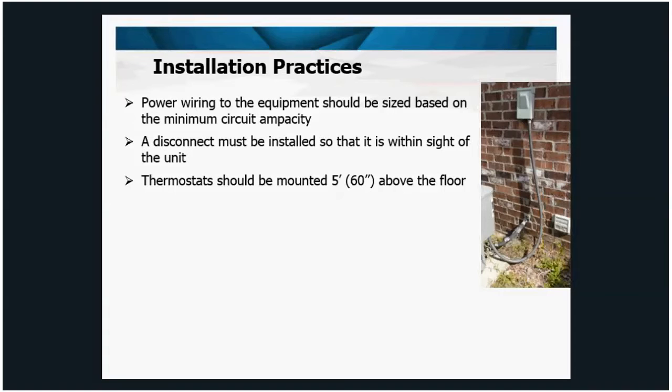Because of that, I think they're going to remove these questions out of the test. I don't know if they've done that yet. So if you see a question, what's the proper height for a thermostat to be set, it is still 60 inches or 5 feet, and it will be until they start pulling those out. The other thing about thermostats will be the position of the thermostat so it's not affected by sunlight or drafts.